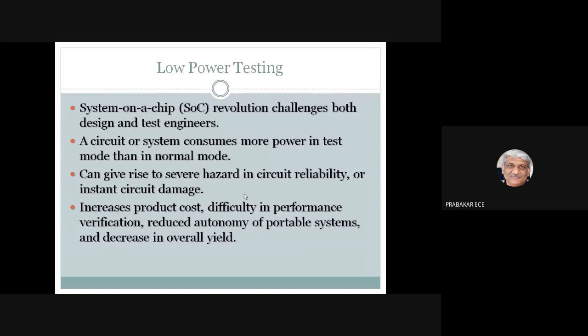Supposing you want to test an AND gate, there are 2 inputs, so 2 power 2, that is 4 combinations, and for the 4 combinations, what are the outputs? If the outputs are right for all 4 combinations, then you can assume that the AND gate is okay. Suppose you have an IC with some 100 pins, then 2 power 100 combinations need to be given as input. Then only can you test your complete chip. So there are test pattern generators. VLSI testing is a separate topic, but you can understand the complexity of testing a logic circuit. That is what we have to discuss here.